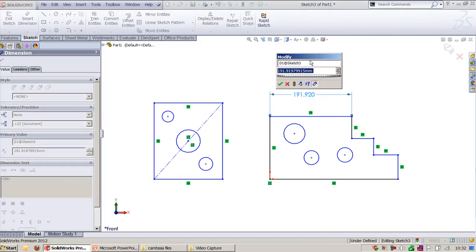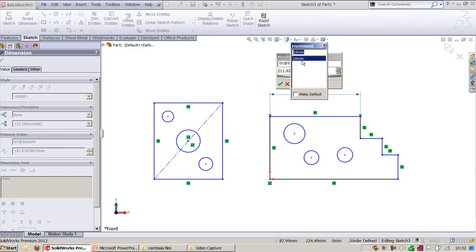In this dialog box you can see a primary variable, which is the name given for the sketch, and you can use the scroll bar to increment it. The increment is 10 mm. If you want to modify it, you can go to the pin increment, enter the value, and that will be the increment value. There is one more option, mark dimension to be imported into your drawing.